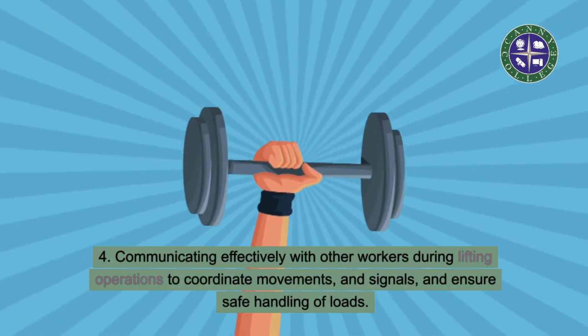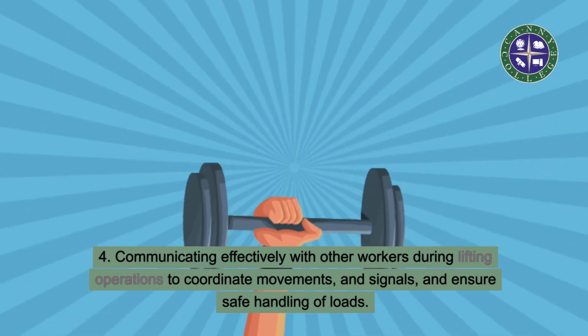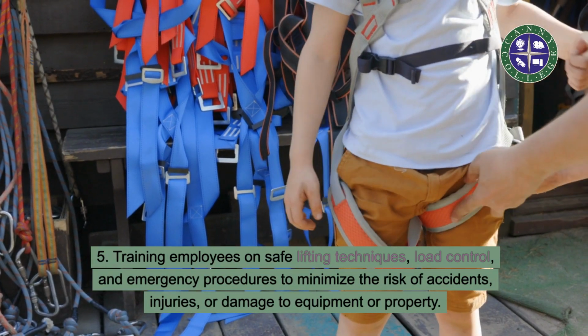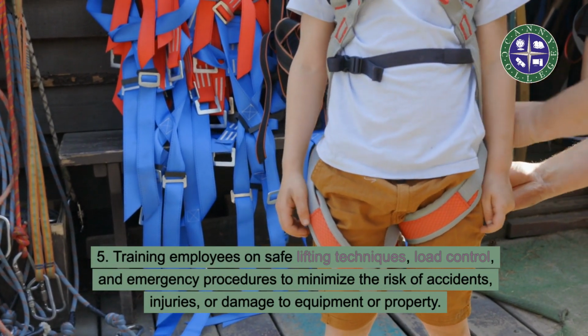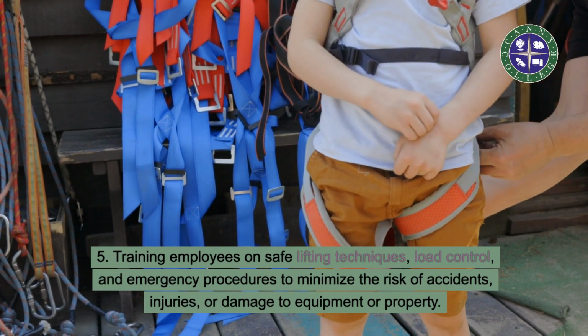3. Ensuring that loads are properly secured, balanced, and within the weight capacity of the equipment being used to prevent accidents and injuries. 4. Communicating effectively with other workers during lifting operations to coordinate movements and signals, and ensure safe handling of loads. 5. Training employees on safe lifting techniques, load control, and emergency procedures to minimize the risk of accidents, injuries, or damage to equipment or property.